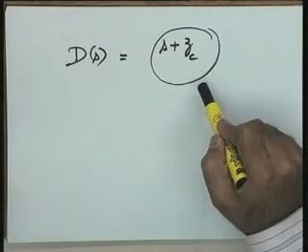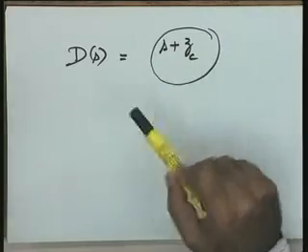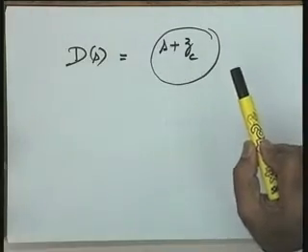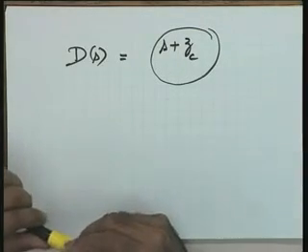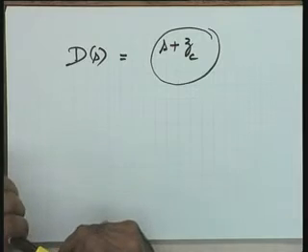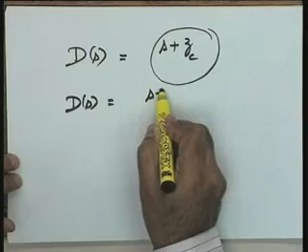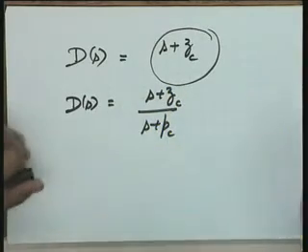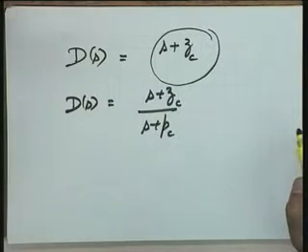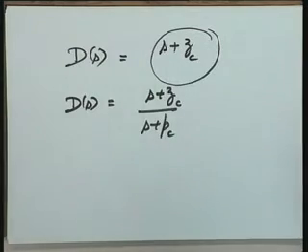Such a controller is prone to noise, and therefore pure differentiators we normally avoid. So adding a high frequency attenuator, adding a filter, is also necessary as far as the complete acceptable design is concerned, and therefore an actual D(s) used in practice is (s plus Zc) over (s plus Pc), where this pole at s equal to minus Pc gives you the filtering effect. That is, high frequency signals will be filtered out. So this pole is very far from the origin.